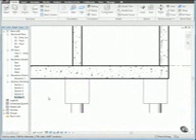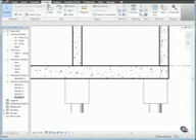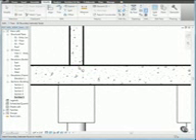And let's add wall keys at the bottom of the wall. Click the Modify tab, and from the Edit Line Work panel, click Cut Profile. Then, on the Options bar, select Boundary Between Faces, and select the boundary between the wall and the footing.